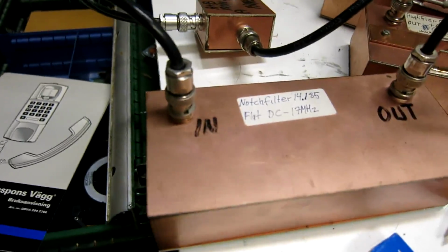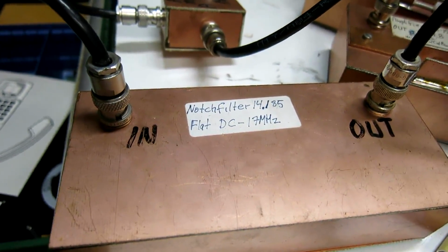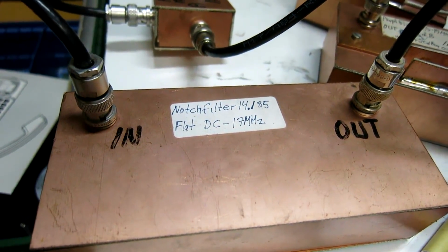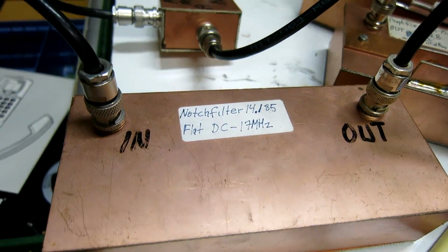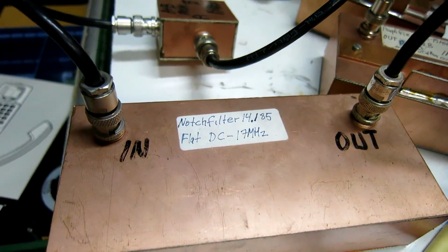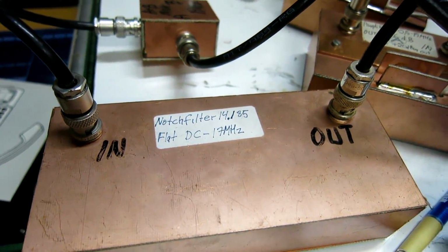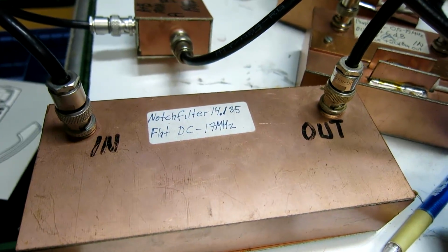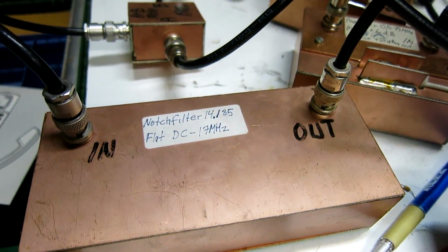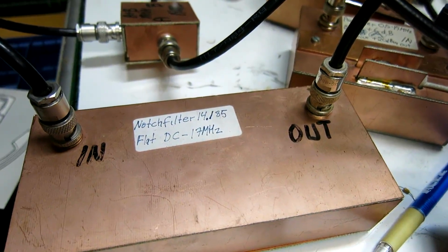And the output from that is sent into this unit, which is a low-pass filter. It has a notch, but it's very narrow and doesn't affect measurements here. But this guarantees that no overtones are reaching the receivers. Overtones might mix with the fundamental and form second-order harmonics, second-order intermodulation, and that is a possible source of measurement errors.